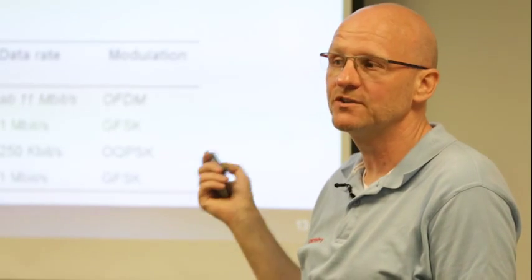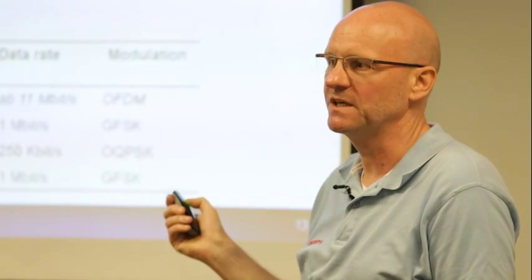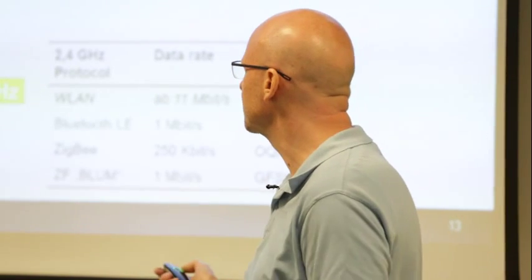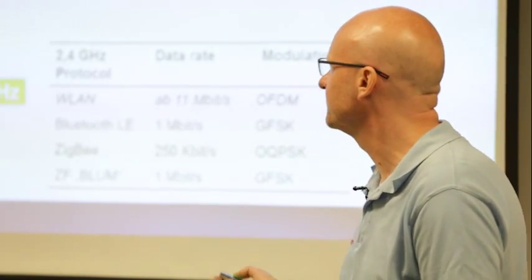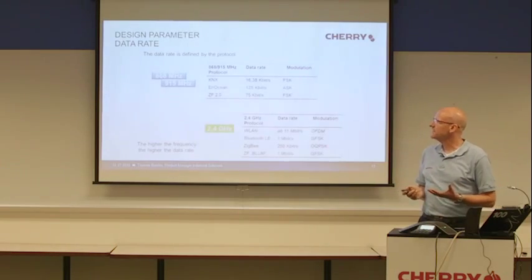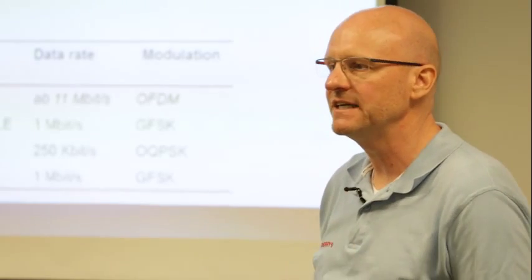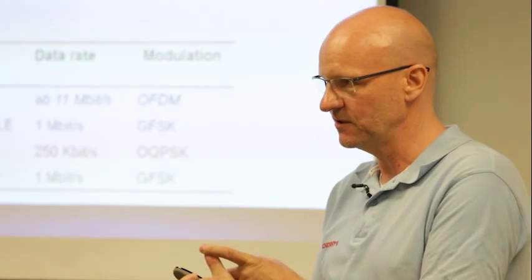And this is a great challenge for RF systems, because when you have a very low data rate, you need much more time for your system to send out data. And time means energy for an energy harvesting system. We will see it later. So you see, data rate is a very, very important parameter for us. And data rate is combined with the protocol.